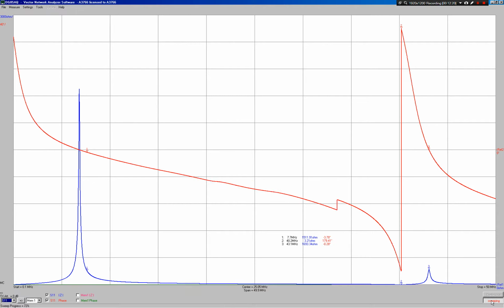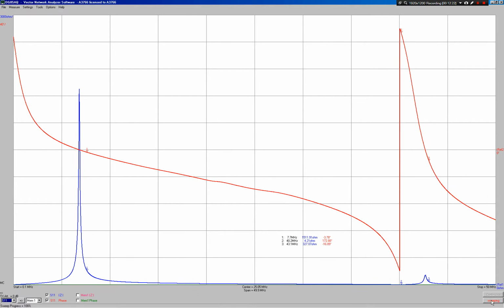Okay, we see that loading. Okay, so everything's shifted down slightly. Now here in the situation, they didn't move further apart or closer. We've put a loading onto that coil, external loading, so we're adding an additional parallel capacitance to that resonance circuit, and we notice that everything shifted down slightly, which we would expect as we start to load additional capacitance. It's literally only the open capacitance of the vacuum variable capacitor, which in this case is about 20 picofarads. And we see the marker was where we were at 1, and we have moved down.